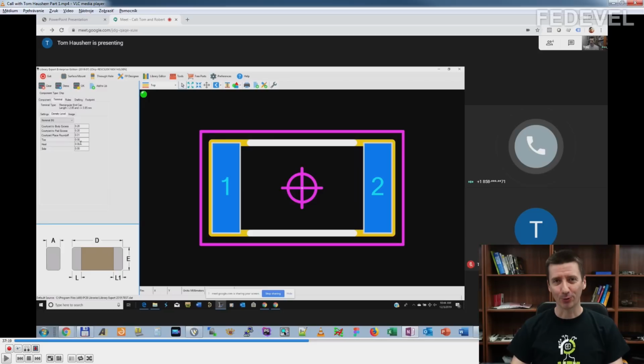Okay, so to make it not so simple, now it is really simple to create a new path. But you actually need to also count with some tolerances. When these components are created, they have some tolerances in the length and width, even the contacts have some tolerances. And then you need to also count with tolerances during assembly and also with tolerances for PCB manufacturing.